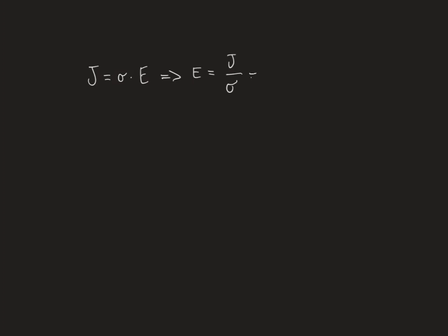This equation can also be written as rho times the current density, where rho is the resistivity, which by definition is given by 1 over the conductivity, or 1 over the mobility times the carrier concentration N sub m times the elementary charge. As for the conductivity, also the resistivity is a characteristic parameter of the material making up the wire.